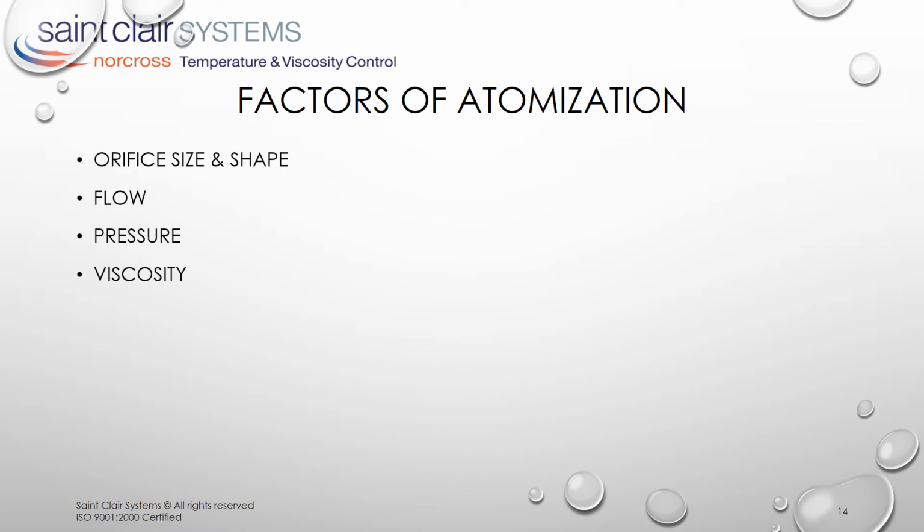Higher viscosities produce larger, heavier droplets, which result in a heavier film build, and film thickness is an important factor in color match. This also impacts flow out and thus surface finish qualities such as gloss.